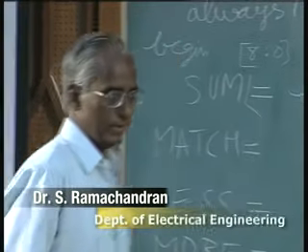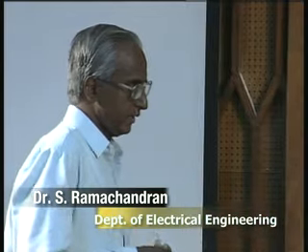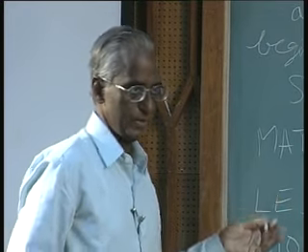That's all the difference. And to summarize the whole thing, we have covered simple gates, the symbol for which is ampersand, OR, that is a vertical stroke, and for exclusive OR caret and so on. And then we have seen how to use assign and always blocks in order to achieve any combinational circuits. In this way you can make any complicated combinational circuits. In the next class we will be seeing how to model sequential circuits.